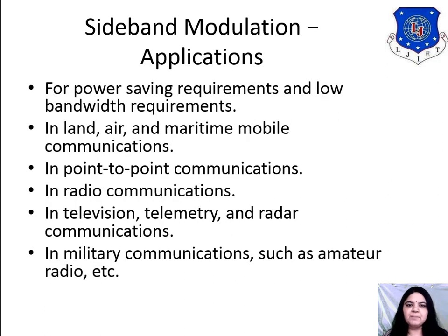There are various applications of SSB modulation. The very first thing that we discussed is power saving. So for applications with a power saving requirement and a low bandwidth requirement, we must go for single sideband modulation.